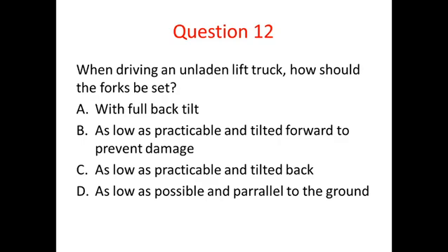When driving an unladen truck, how should the forks be set? So when you're driving a truck with no load, how would you position the forks? Well, you would need to have the load as low as practicable and also with back tilt. So the back tilt is going to be dependent on the ground conditions that you're dealing with. If it's slightly bumpy, maybe you want just a little bit of back tilt. If it's particularly bumpy, you'd want more back tilt, of course. But generally, you just want to have a little bit of back tilt.